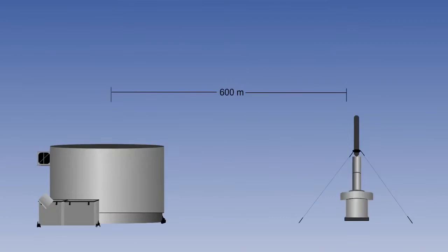For an en route VOR, the maximum is 600 meters. If the VOR and DME are not associated, for example, a terminal DME which is more than 100 feet from the VOR, but they are using the same location, then the first two letters of the equipment are the same, but the third letter of the DME is the letter Z.